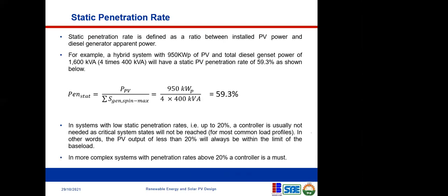Sorry, by controller, are you referring to another controller, or the charge controller we just discussed? No, thank you for pointing that out, not the charge controller. You need a controller that senses your demand. If you have a solar system and a generator, you need a controller to know when the generator comes on, depending on your demand, and when the generator goes down. You need a controller to blend the supply from the grid and from the generator. Those are what the controller does for you, not the charge controller, please.